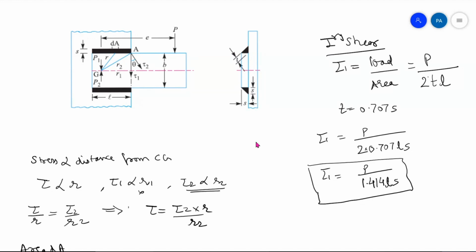If you remember the design of bolted joint, we had seen that the bolt which is at the farthest distance breaks first. Okay. Similarly here also, where will the weld start failing? It will be at the distance which is farthest from the CG, and the distance which is farthest from the CG you can see here clearly from the sketch is R2. Because if I talk about G joining this point, then this distance will be obviously less than this distance. Okay, so we have to always find R2. R2 will not be given in the exam, it will not be given in any question. R2 has to be found by us. Okay, and why R2? The reason I have explained. Because R2 is the farthest distance.